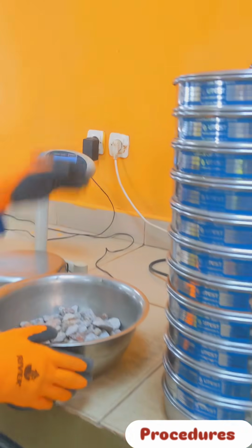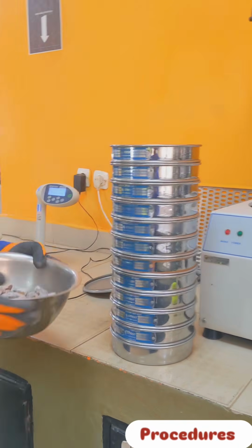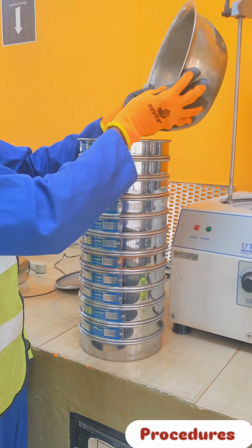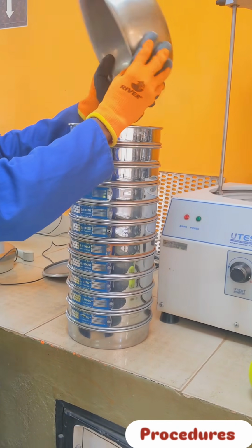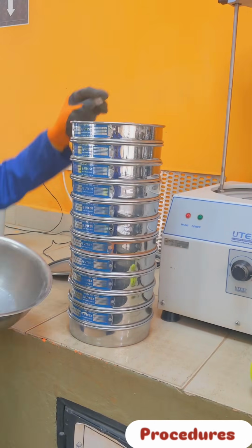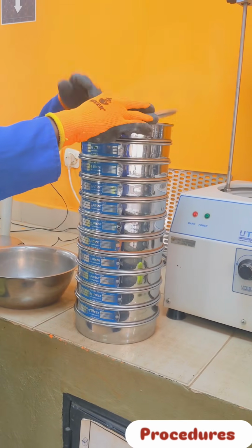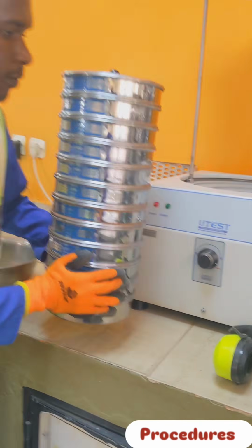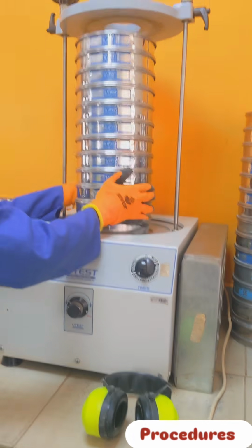The third, pouring the sample onto the sieve. Before doing so, ensure your sieves are stacked in descending order from the largest opening at the top to the smallest at the bottom, with the pan underneath. Now carefully pour the sample into the top sieve and cover it with the lid. Anyway, you can find the exact sieve sizes listed on the recording sheet. Let's get ready to shake.